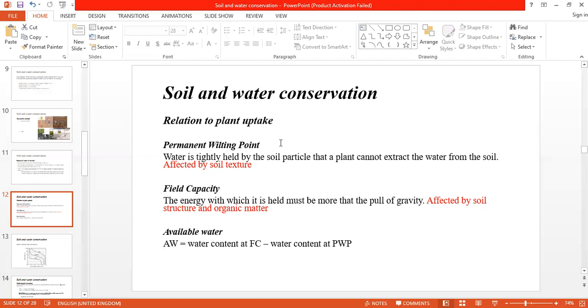So what happens will be this. Let's say that we start from a dry soil. You've measured your matrix potential at permanent wilting point. So you start to irrigate, you reach field capacity, then you say, okay, now the extra water that I'm putting will be wasted, so you stop. Then the plants will start to use the water, so you start to monitor it. It will start dropping.